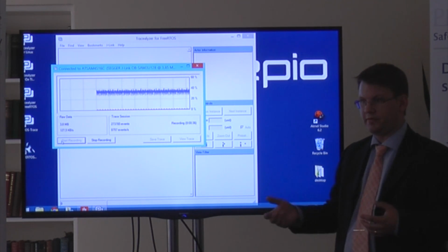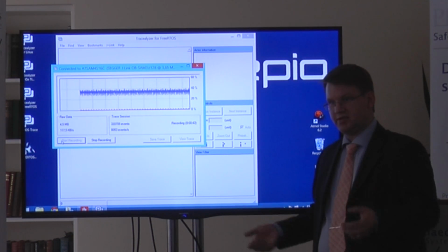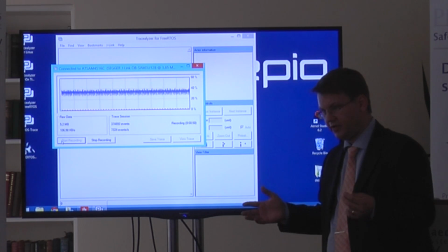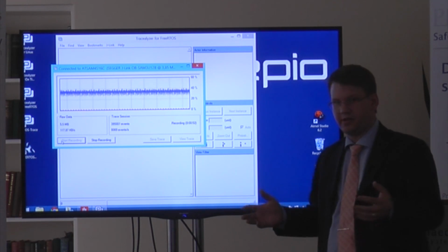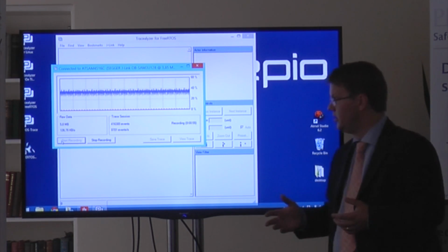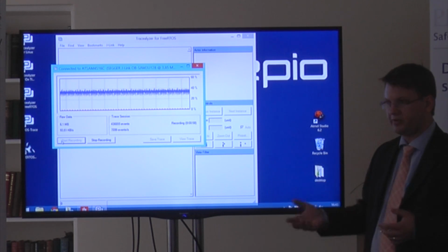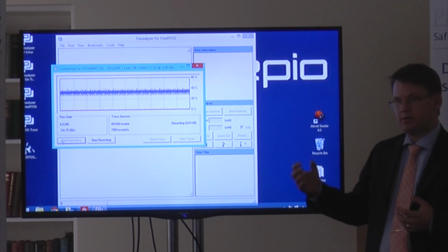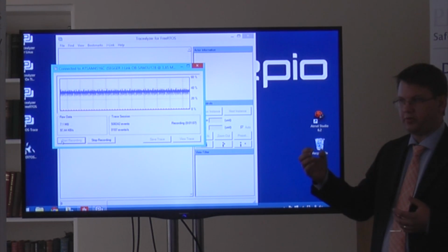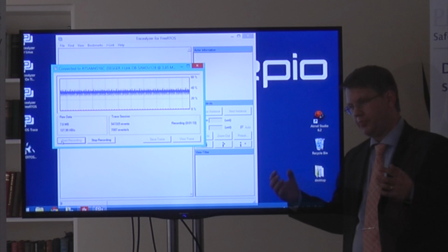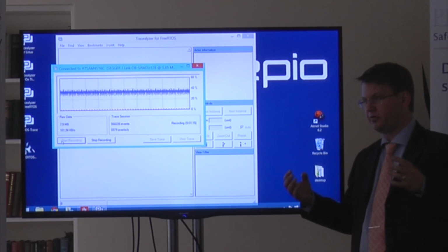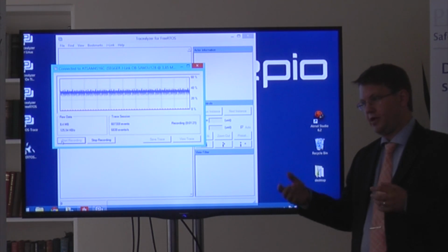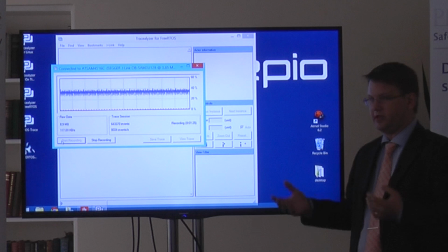If you have a 1 terabyte flash drive, you can store days or weeks of trace this way. This is not function level trace. It's not instruction level trace like you get with ETM or ETB from the processor. This is software-defined trace, meaning that we have instrumentation that records selected points in the system. We have a pre-packaged instrumentation layer for FreeRTOS and other supported operating systems, which you just include as a header file, very simple. So you don't need to do all this instrumentation yourself.